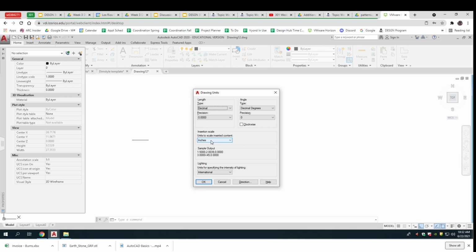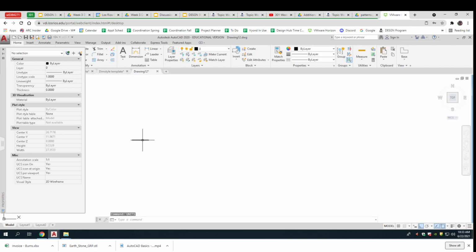I have personal experience with that in both Europe and China, where I got tiny parts because their machines automatically read it as millimeters and my drawing was in inches. I got tiny parts because it did not read this. So always make sure that people know what you're talking about, and you'll see that on your stuff. So that's what units are for.